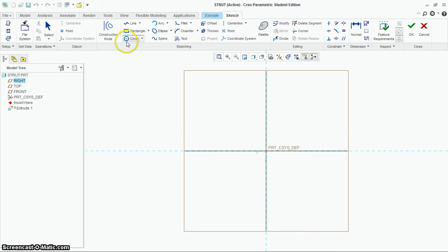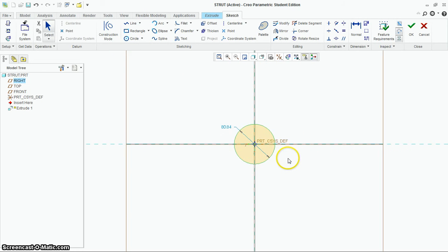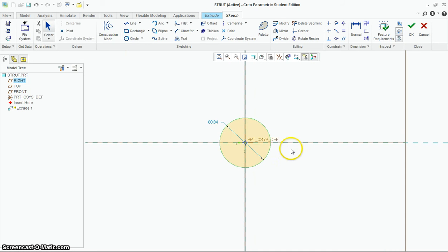We're going to go ahead and start with a circle. And this circle is going to be a diameter of 8. We don't know how big that circle is when we initially draw it. So once you middle click, you can see these weak dimensions. Let's talk about dimensioning here real quick. Obviously we have the correct type of dimension up. It's a diameter dimension.